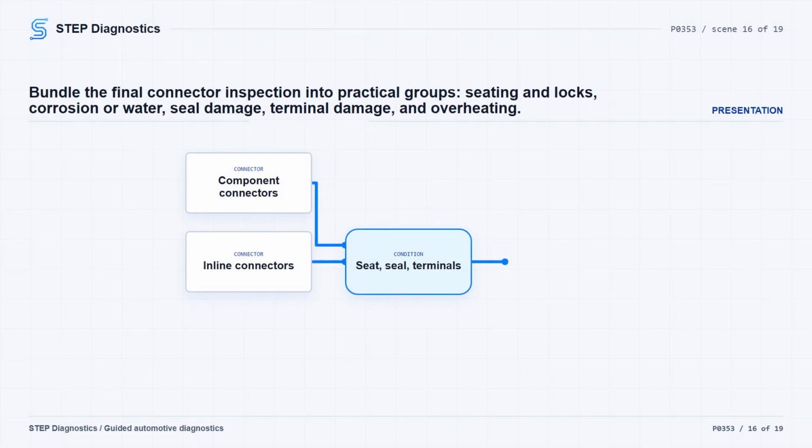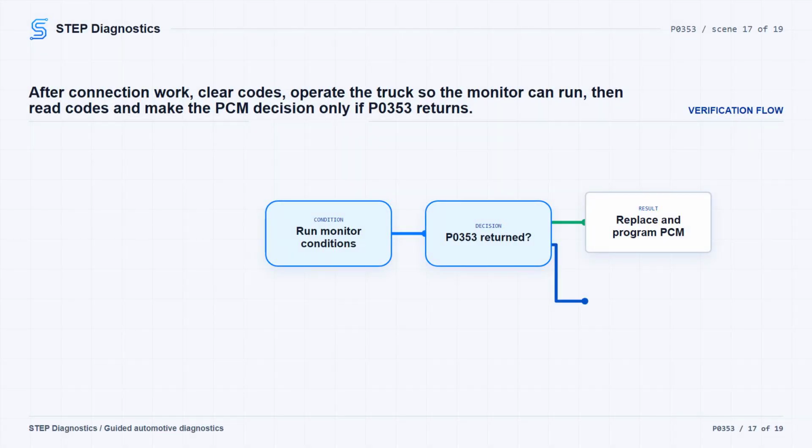If the coil swap check does not move the fault, check the related PCM and component connections. Perform any applicable service bulletins. Disconnect the PCM connectors, any related inline connectors if equipped, and the related component connectors. Inspect for poor connector installation, damaged locks, corrosion, signs of water intrusion, damaged seals, bent terminals, overheating from poor connection, push-back terminals, spread terminals, and poor terminal tension.